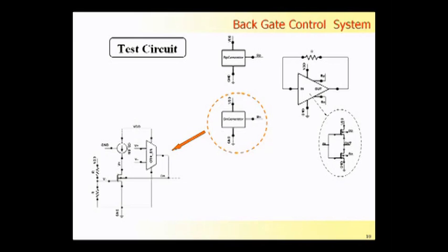It's constituted by a current source that is stable in temperature and bias variation, and a differential amplifier. This feedback circuit has to provide a voltage able to maintain this current constant. So if I mirror this voltage on the NMOS transistor inside the LNA, and the same for the PMOS, I can have the same constant current also in this section, so in the amplification stage.